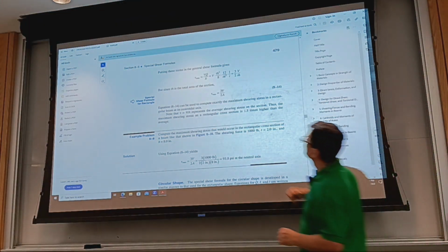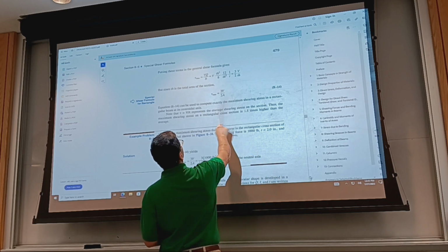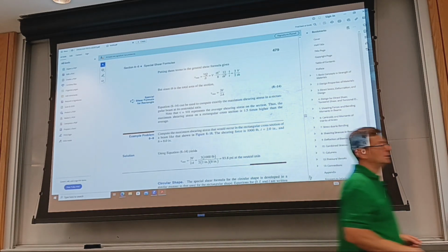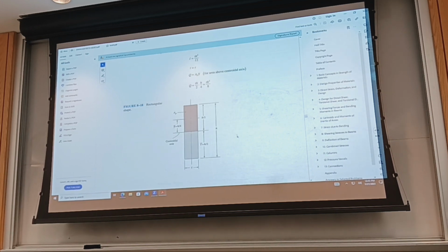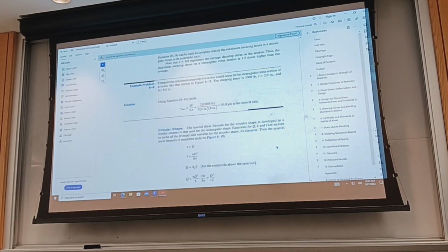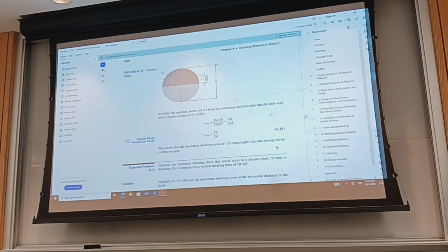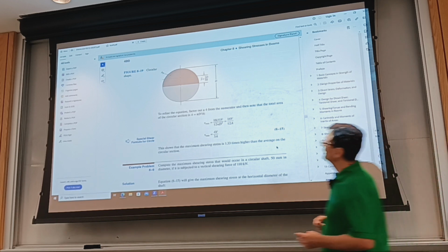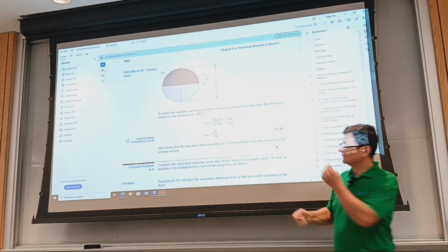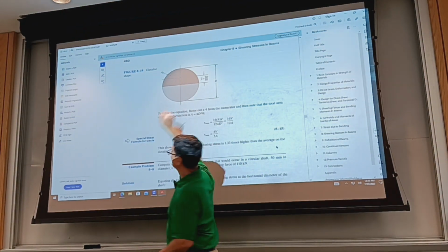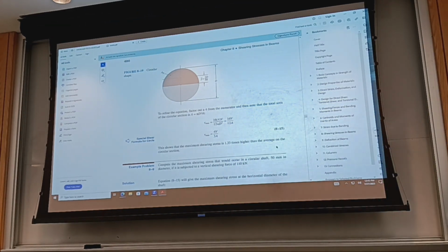So it says here the exact maximum shear stress due to shearing force for a rectangle happens at the centroid. For a round solid bar, likewise, we have an exact formula, 4/3 shear force over total area, and it happens likewise at the centroid. And then we have an approximate equation that is given. Just one.